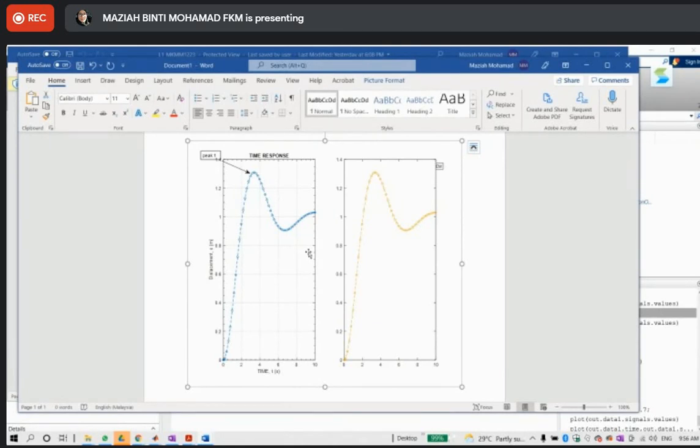And then we have seen the response, the scope, how to plot it in MATLAB, and then how to tune the PID PI controller. Okay, use PID auto tuner. All right, and then I showed you how to edit your figure. Okay, I hope you can explore the plotting function there. Okay, so I think I will stop here.